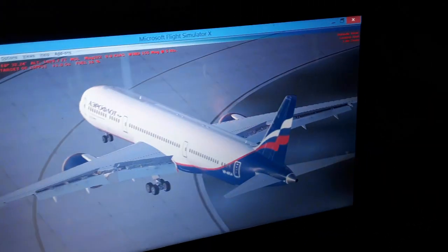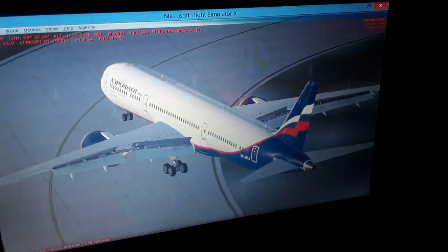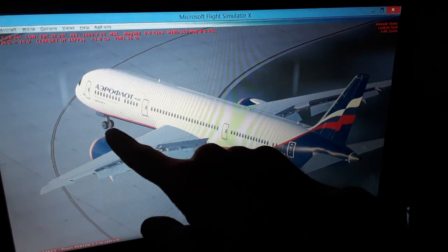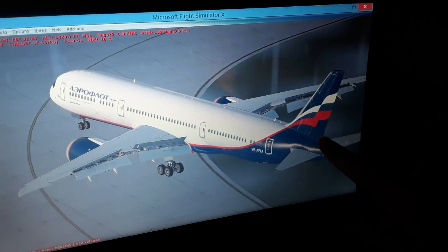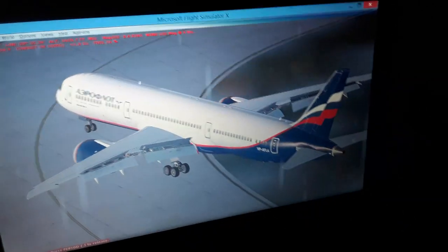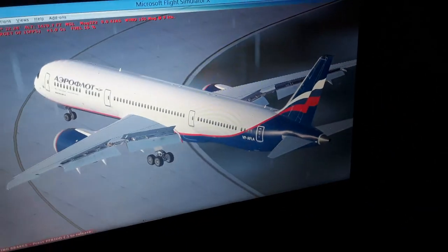So the tiller and the nose wheel is decreasing from 76 degrees from 45 knots when the rudder is coming in, to 7.6 degrees all the way up to 70 or 80 knots. It deactivates. So we have only the rudder above 80 knots for directional control of the aircraft in takeoff and landing, also in the air.